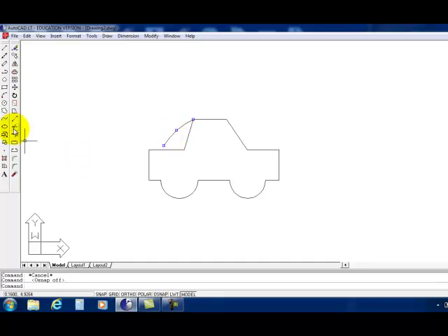The other function I wanted to show you was to lengthen the line, so extending a line. So if I choose this one here, and it's going to ask me to select the boundary edges. So I'm going to make this the line where I want the line to stop. I'm going to be bringing this arc down. So I'm going to choose this one, hit enter, and select the object to extend. And when I click on this one, it should meet up right against the other one like that. Hit escape to get out.